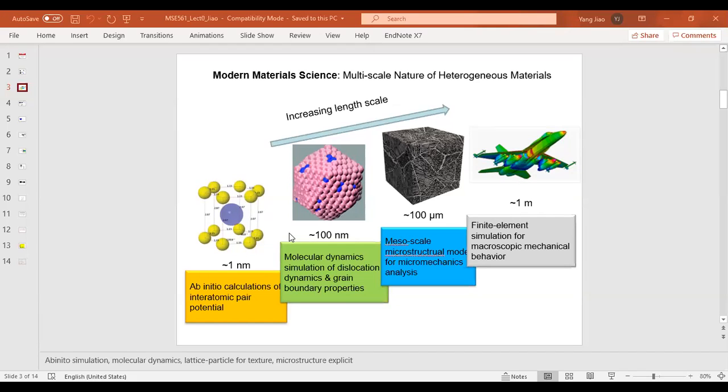So all these complex length scales of microstructure features together give you the performance of the material. And every single phenomenon you see in the material behavior, for example, the fatigue initiation, the crack initiation, or things like that, is going to go all the way starting from atomic level and propagate up until we can see this crack in the macro scale.